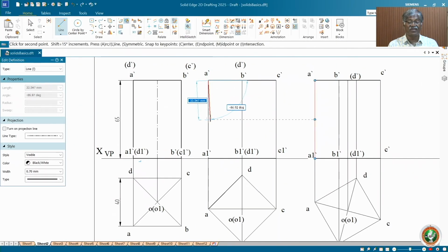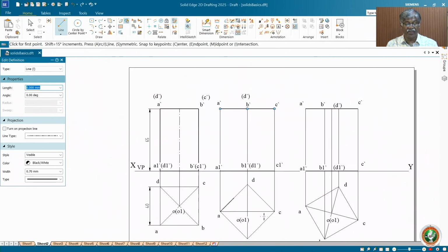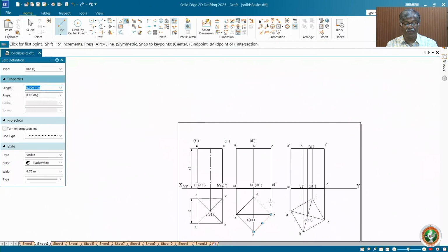Now what about the lateral faces, the lateral edges? Here I have AA1 visible, BB1 visible, CC1 visible, but DD1 exactly coinciding with BB1. There is no scope for either the axis or the hidden line, so it is all visible lines. Select all lines.